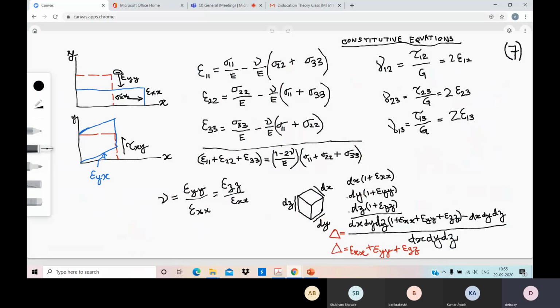Similarly, if I give you stress tensor, you can calculate strain tensor. If I give you strain tensor, you can back calculate the stress tensor, and from that you can derive whether yielding will occur or not. So if you see in a body some amount of displacement, because we said that ultimately things that we measure is displacement. Inside a bridge, we put certain gauges.